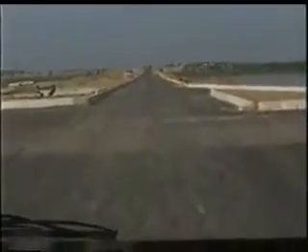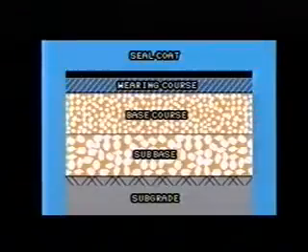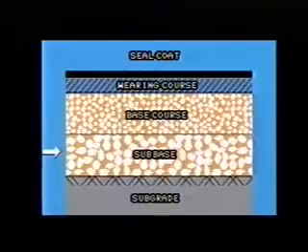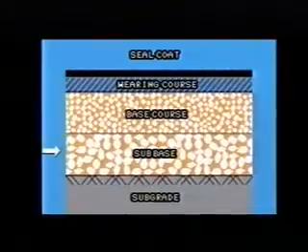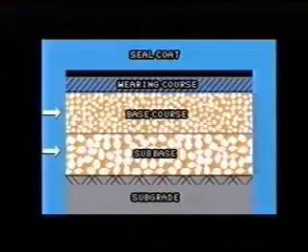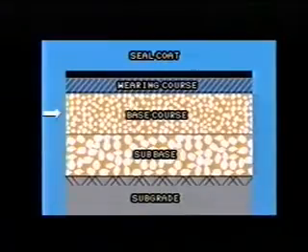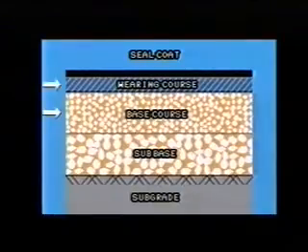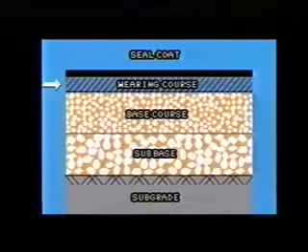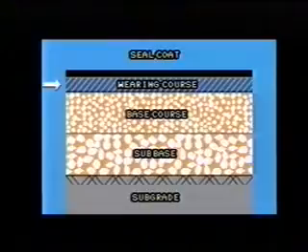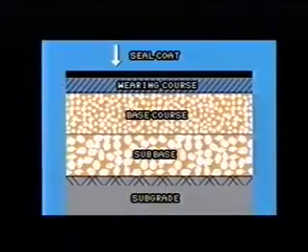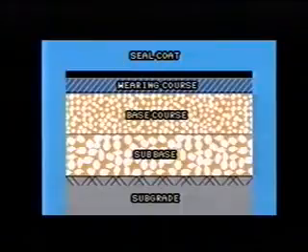In order to understand the concept of flexible pavement design, let us have a look at the component layers of the pavement structure. The different component layers of the flexible pavement comprise sub-base, base course, wearing course, and seal coat constructed over a prepared soil subgrade.